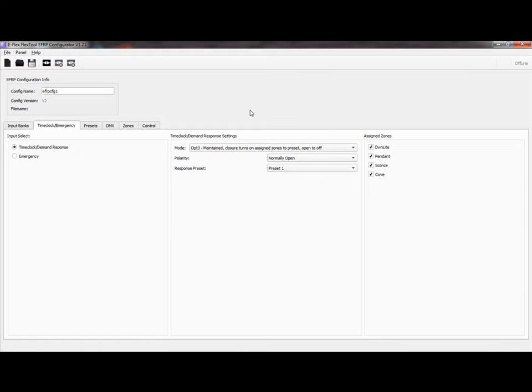In this video, we'll show you how to set up the time clock / demand response input on an eFlex relay panel. Select the time clock emergency tab and select the time clock demand response input.